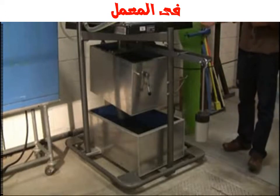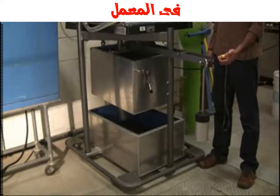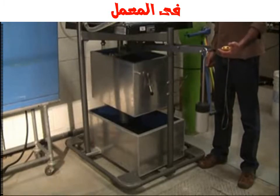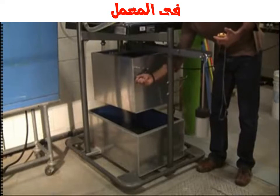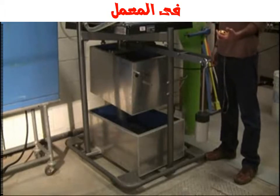After doing so, ensure there is no water leaking from the bottom of the tank. Turn off the timer as soon as the balance tips over. The time recorded is the time required to accumulate 9 kilograms of water. Remember to unplug the tank by turning the lever clockwise in the horizontal position so that no water accumulates in the tank before starting any more runs.